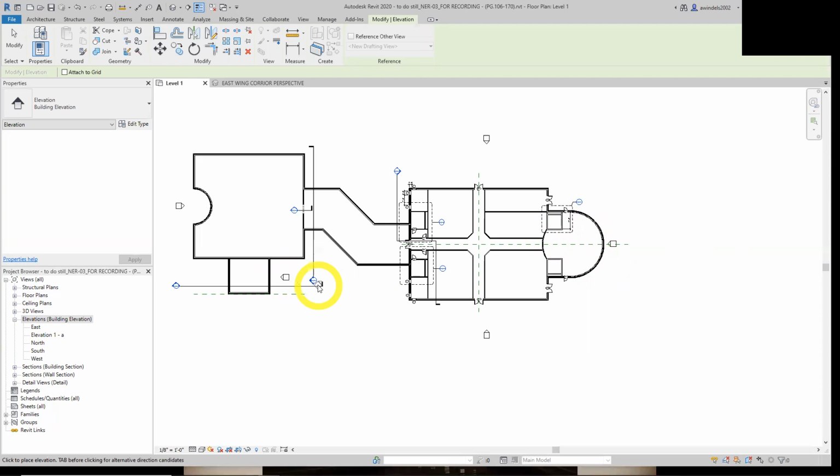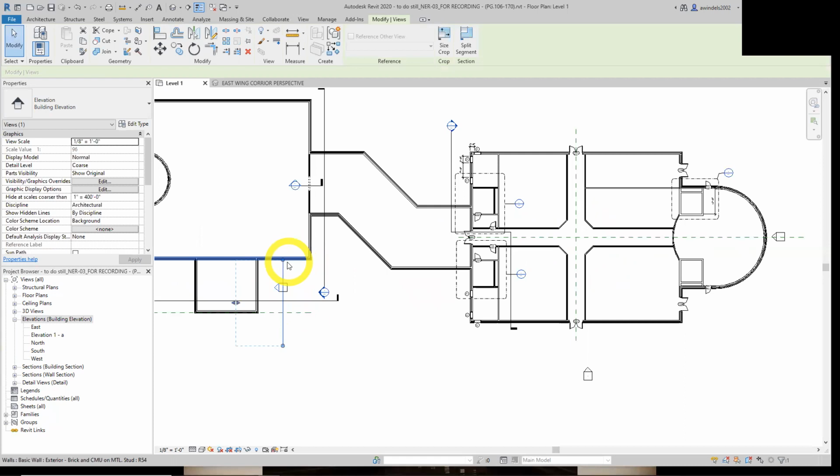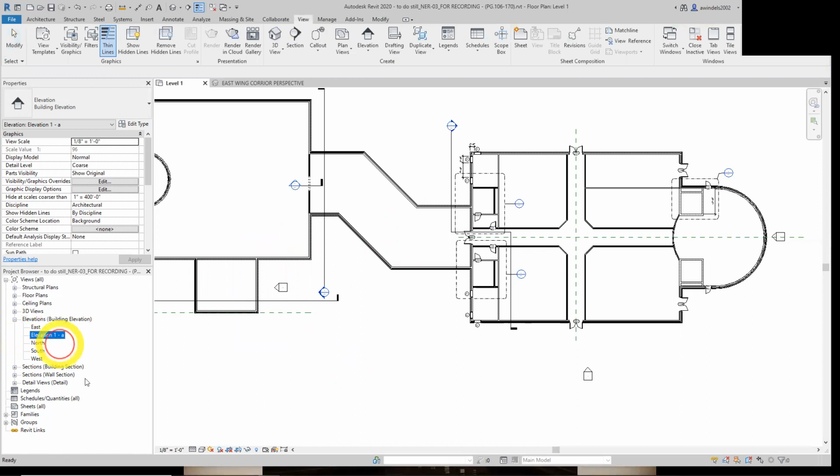And let's see what that just did. So let's select a triangle. Like I said earlier, that's what activates the view, and it says what are we viewing. So I'm going to drag this. This is my new elevation view, about like that. And it was created here as a new elevation view. I'm going to call that west wing, south east elevation. And let's open it, see what it looks like.